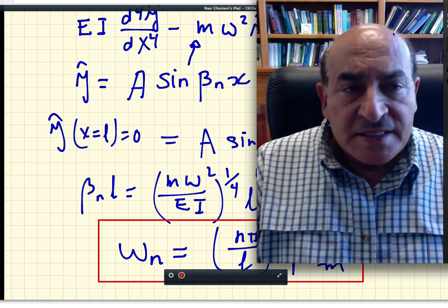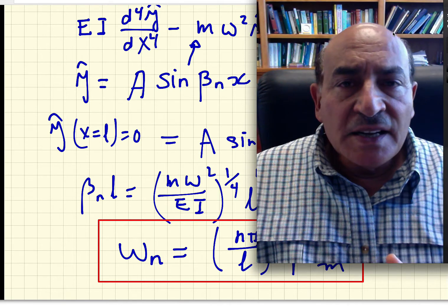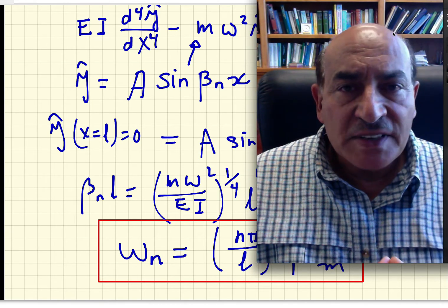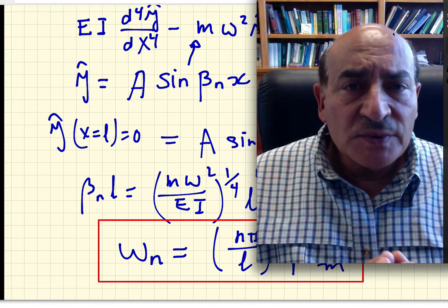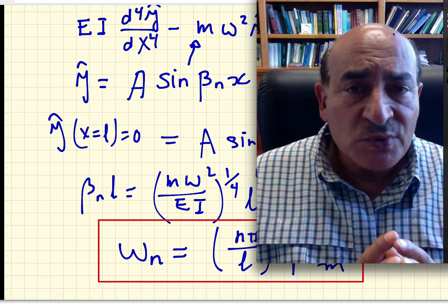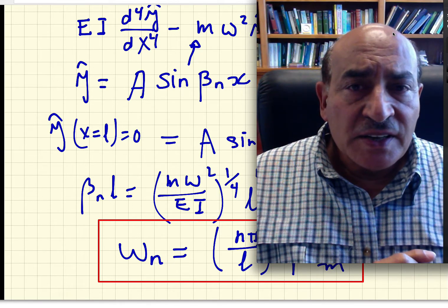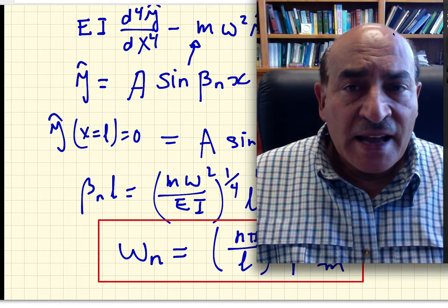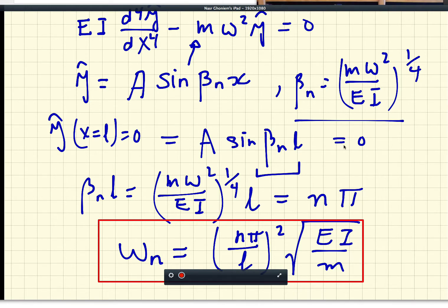So that's kind of the simplest. I went through it a little bit quickly because we didn't want to cover too many different boundary conditions. It can give you some different answers. This will be for a boundary condition where we have a shaft that is simply supported on both ends. We can find now the critical speed of the shaft without having any masses attached to this shaft. So now we can move on and look at the other situations.